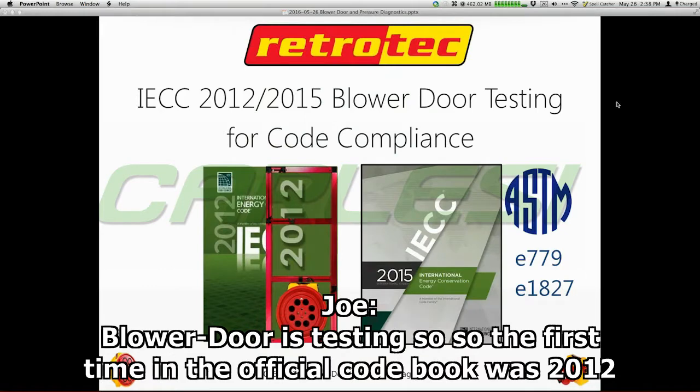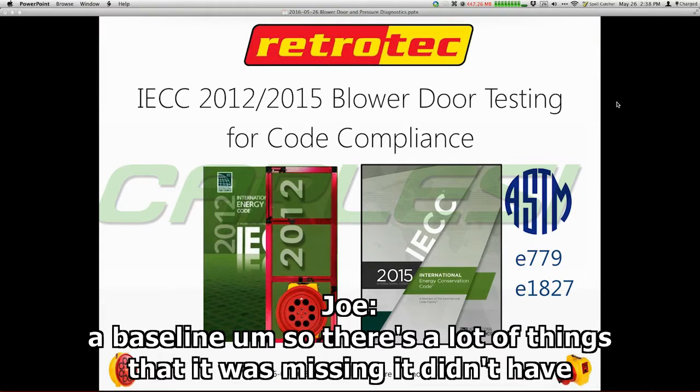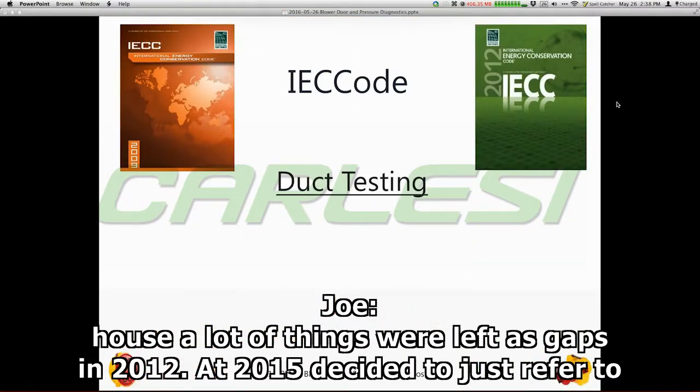The 2012 code was the first time the official code book required blower door testing. And it actually was very controversial in terms of what its requirements were, because they were just a basic test. It didn't even require a baseline. There's a lot of things it was missing. It didn't have anything about how accurate your equipment needed to be or how to really set up the house. A lot of things were left as gaps in 2012.